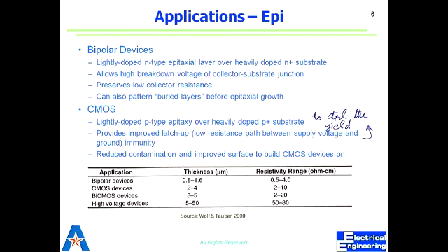And one can argue, why do we have to grow on top? If you have N+, we can just diffuse it down or implant it down, but we don't get control over the concentration of dopant. So we have to put up another layer and define our own doping concentration in that. And it can also create a buried layer below what we grow on top.